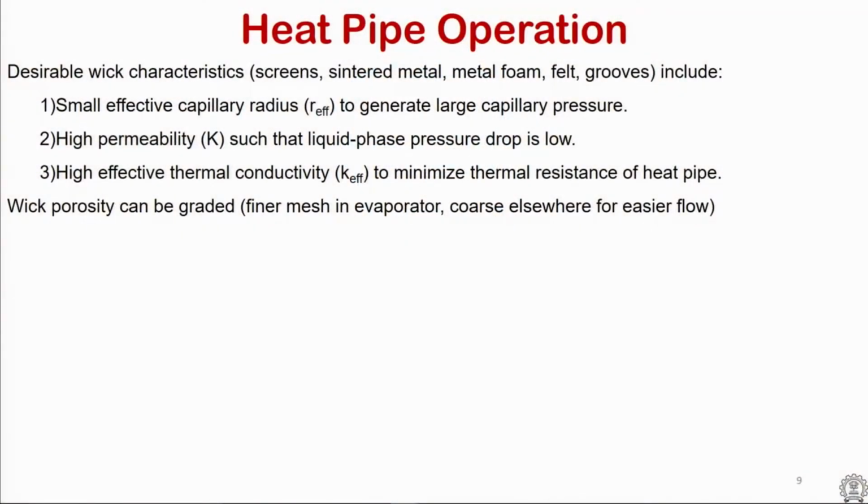So, these are the desirable properties of the working fluid, and in terms of wick characteristics, one desires always, at least at the evaporator end, a capillary radius that is as small as possible, because the capillary pressure driven is inversely proportional to the capillary radius of the wick.